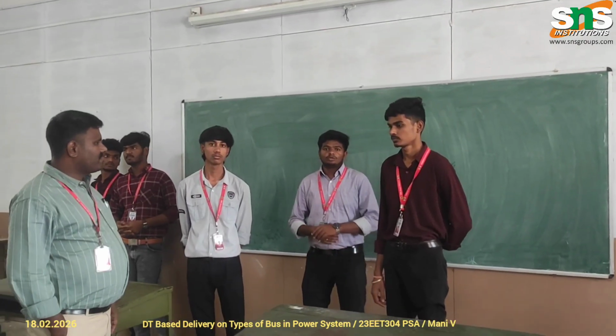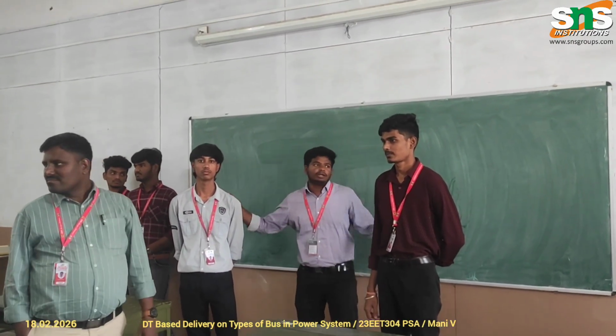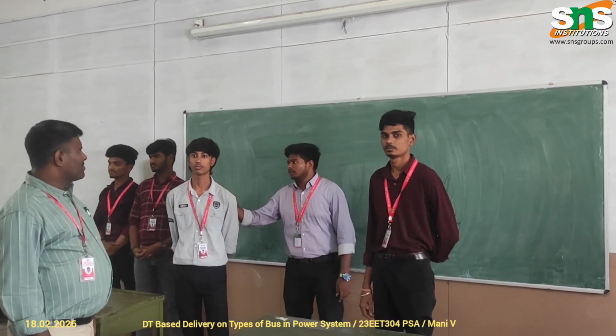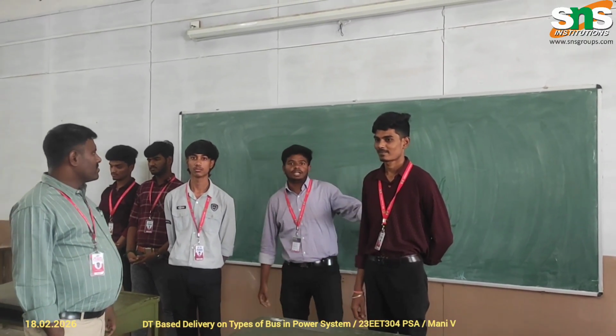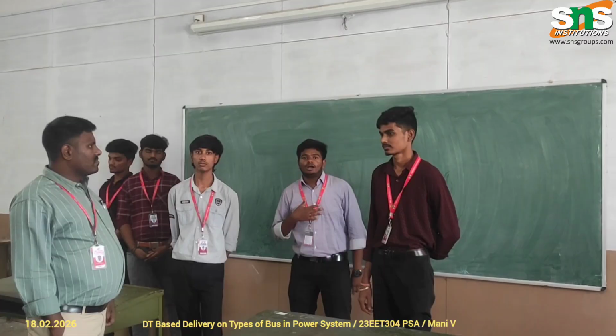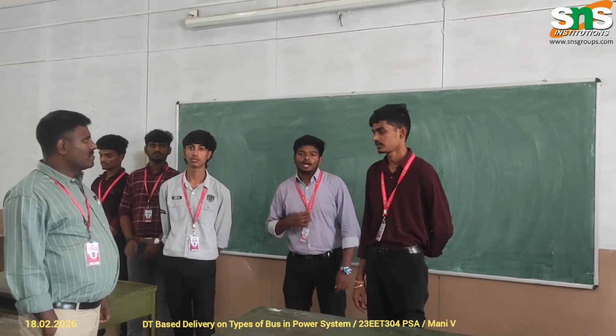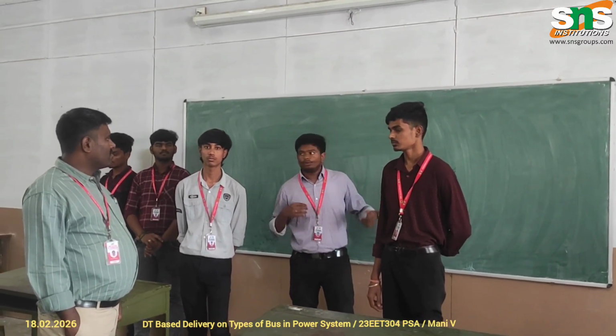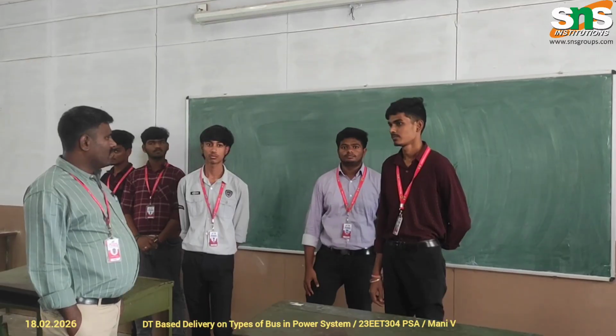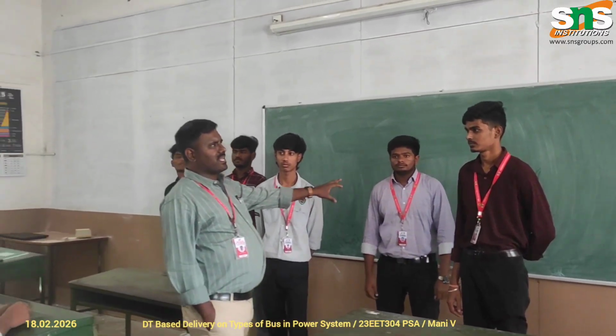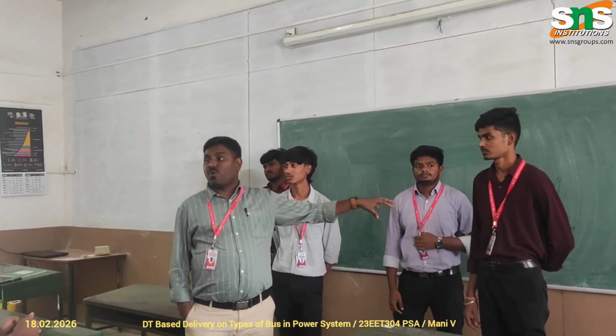Now the second bus is the load bus. I know the value of real power and reactive power; the notation of real power is P, and the notation of reactive power is Q, so it is also known as the PQ bus. I want to determine the magnitude of voltage and the phase angle. So the second bus is nothing but a load bus.